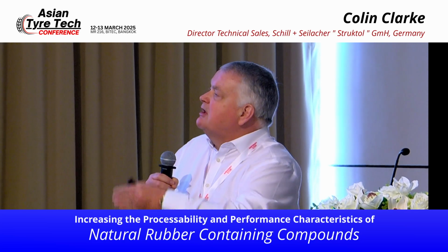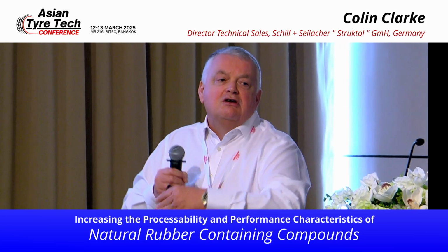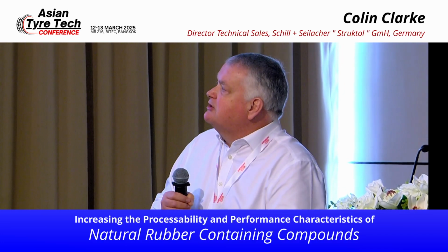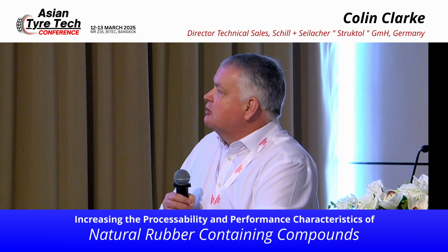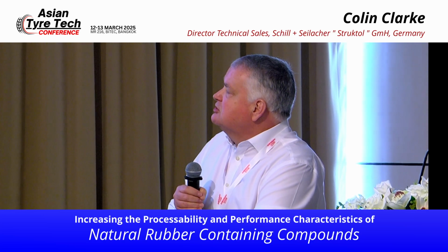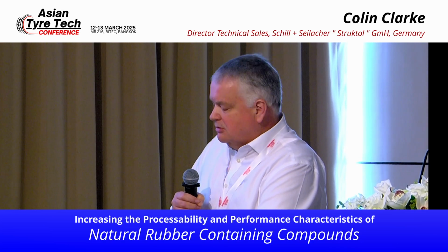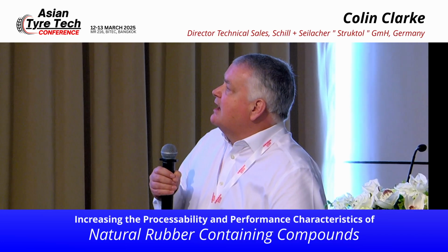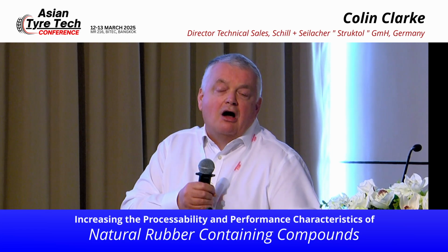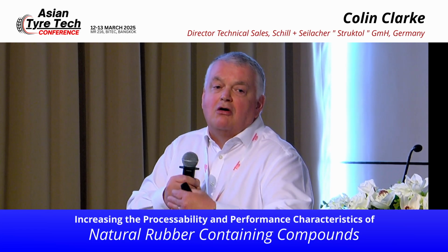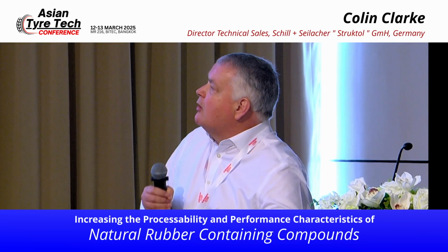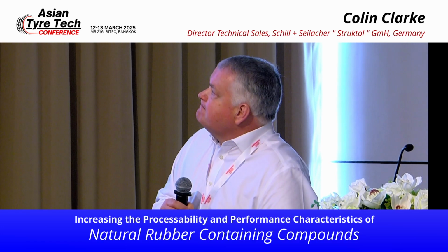We see a little bit of slip action at the start, the torque falls. Slip between the rubber and the rotors. Physical peptizer is very rubber soluble. It's absorbed back into the rubber very quickly. So we see the torque return. But it pretty much follows the line of the mechanical mastication. So virtually no breakdown at all. And then finally, if we add in then the HT105, the new generation peptizer, it pretty much follows the line of the chemical peptizer. So it has a strong efficiency to reduce the viscosity of the natural rubber, to reduce the energy required for mastication. What does that mean?